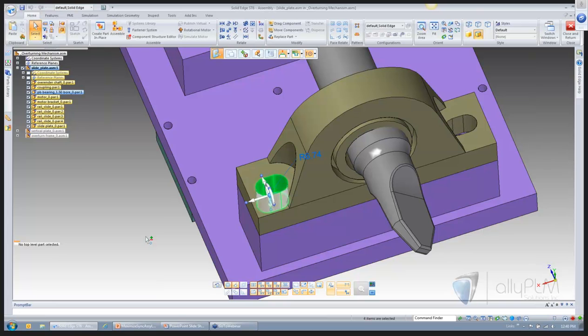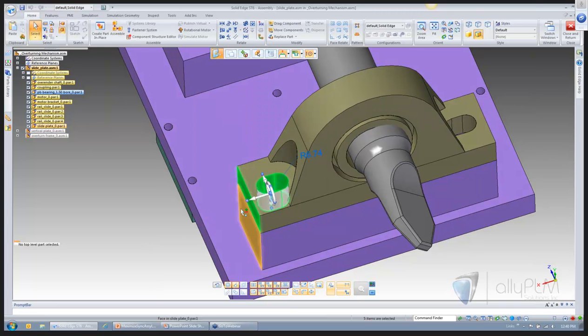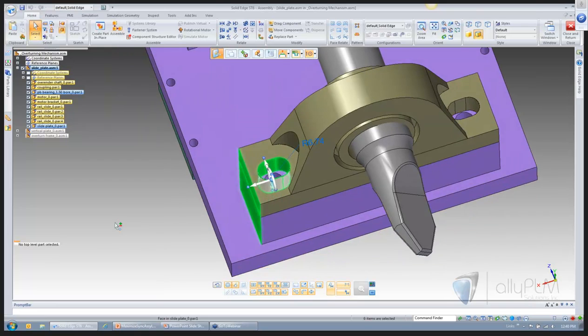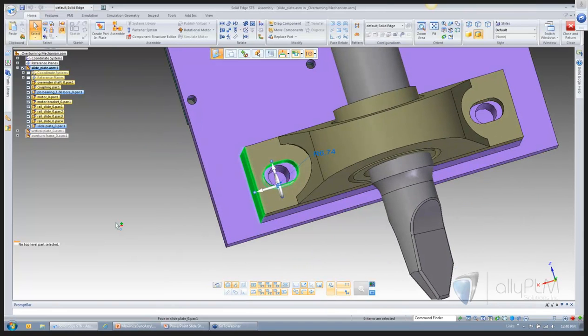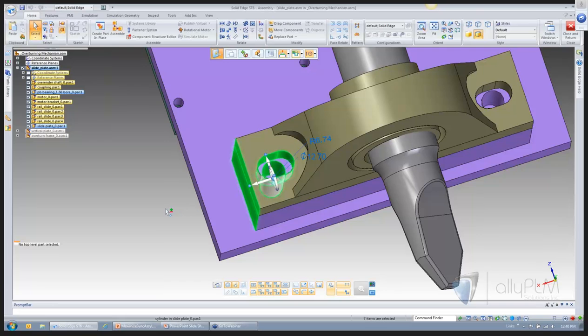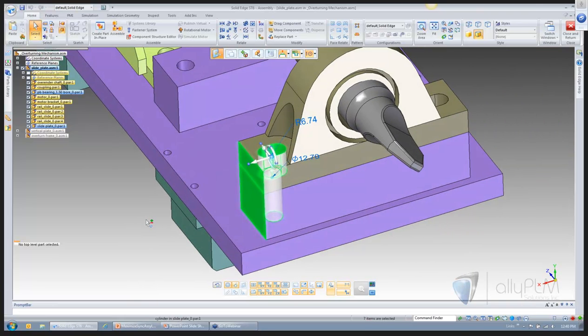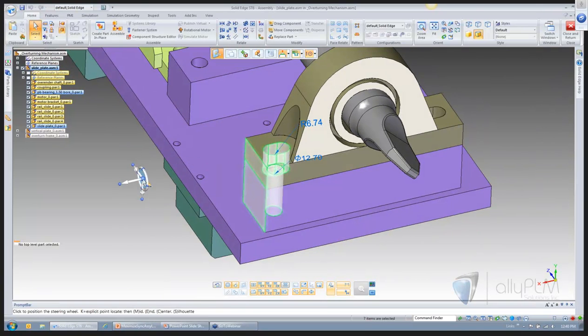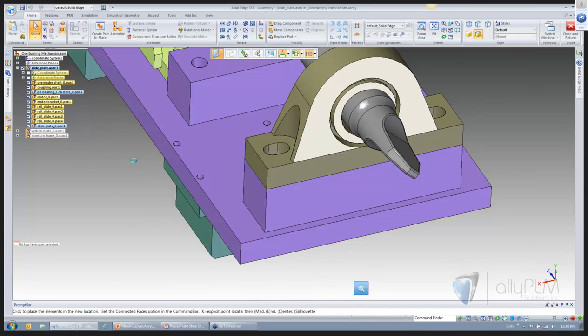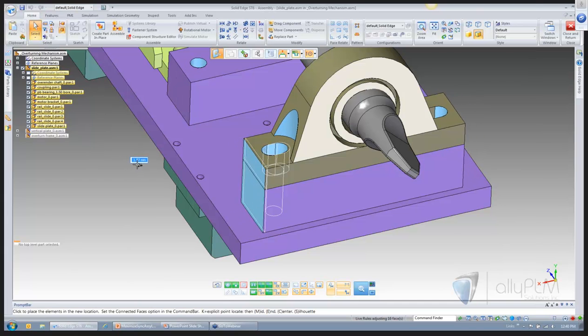and I'm still in the Add Remove. So I do need these exterior faces to go along for the ride. And then in the block, the support block, there's also a mounting hole. Now I have a select set of everything I intend to move. And I'm going to move the origin of my steering wheel because it's something we're going to talk about later. When you're making a delta move, meaning all I care about is the distance of the move, it doesn't really matter what my origin or my destination point is. But there are times that we do care about this.